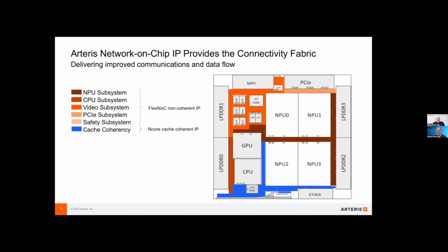The source data will start off the chip. It will be moved into DRAM. It will be partitioned off for processing to processing elements on the system that may be coherent. That data will end up back in the DRAM. That data may be moved to other parts of the system like a display, and that's streamed non-coherently then to the display, while the coherent system is then again in parallel taking on more data, doing more processing.